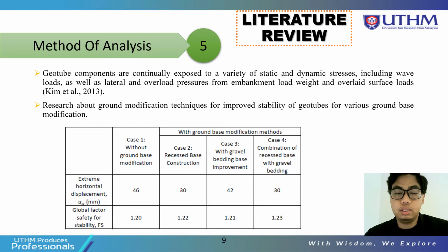A method of analysis in literature review from Kim et al. in 2013 stated that geotube components are continually exposed to a variety of static and dynamic stresses, including wave loads, as well as lateral and overload pressure from embankment, load wake, and overlaid surface load. So, the table below shows the research about ground modification techniques for improved stability of geotubes for various ground waste modification. They conducted 4 cases, and the results they got are displacement and global factor of safety for stability.